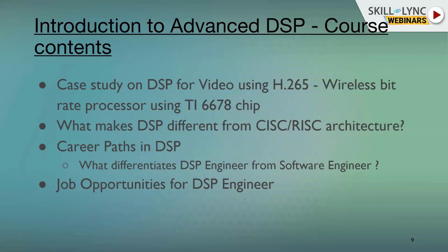The second thing is that when using a DSP architecture, the memory is limited to something like 1 MB or 256 KB in some cases. And this memory is within the same chip, within the same core. With this approach, it's going to speed up your memory access every time. Okay, that's the second thing.